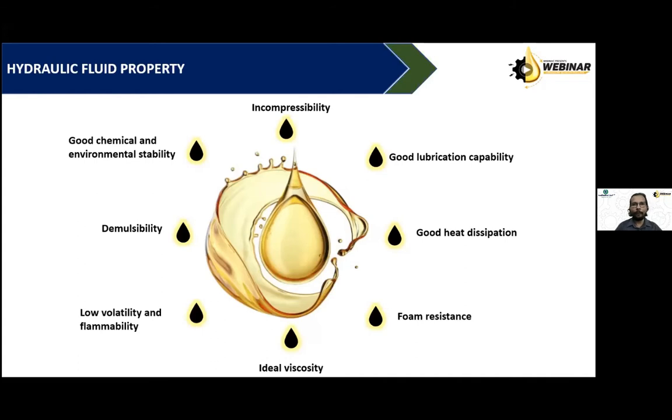First, oil should be incompressible, whatever the hydraulic application is, because incompressible oil can transmit the maximum of the power gained from the source. If it is compressible, then part of the power will be used to get it compressed, and the ultimate output will be lesser than the input.